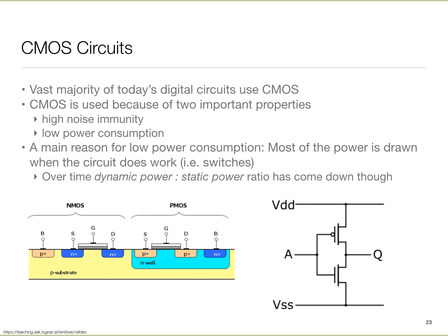Most of the digital computers, digital systems that we use nowadays are built around silicon with the CMOS technology. And the reason is that they are very robust to noise and also because they consume very little power. And the reason they consume very little power, so this is a silicon level view, but at a very high level, these circuits are basically switches. These transistors are essentially switches.